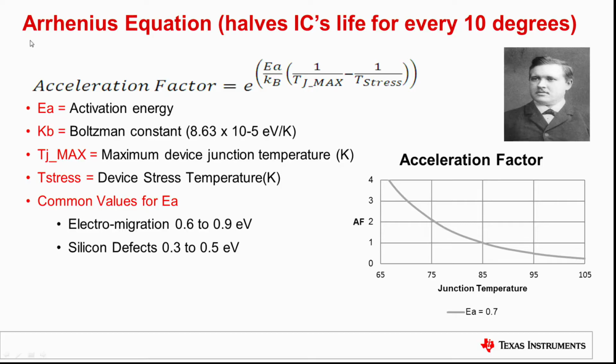When we think about lifetime, most people in our industry think of Svante Arrhenius, a Swedish chemist, and he came up with an equation that basically breaks down to the speed at which a chemical reaction would happen. And what we in our field have done is we've come up with common values of activation energy for electromigration, silicon defects, and other types of failures.